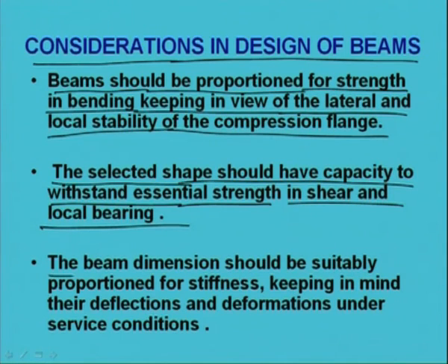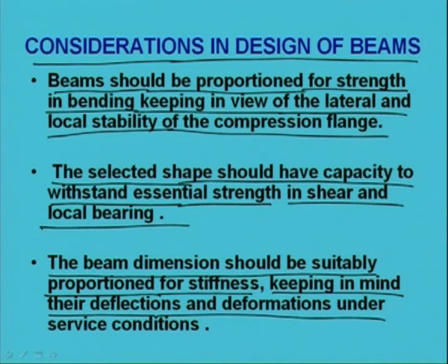Another point is, the beam dimension should be suitably proportioned for stiffness, keeping in mind their deflections and deformations under service conditions. That means, dimension of the beam should be proportioned for stiffness keeping in mind the deflection and deformation under the service load.